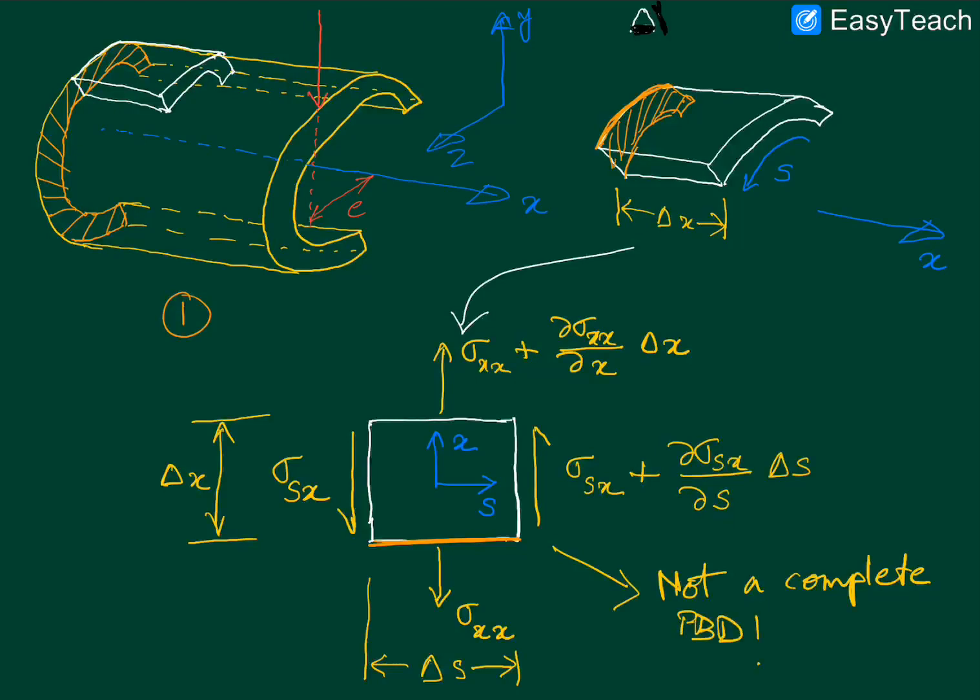This is not a complete free body diagram, because we have only depicted the stress components along the x direction. We are going to write down the force equilibrium equation along the x direction, but in reality there would be other stress components along these various edges. We're just not depicting them.